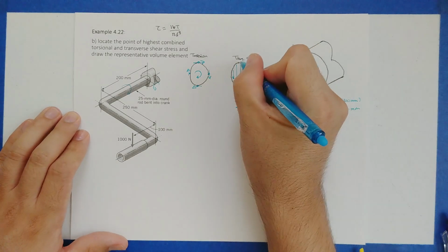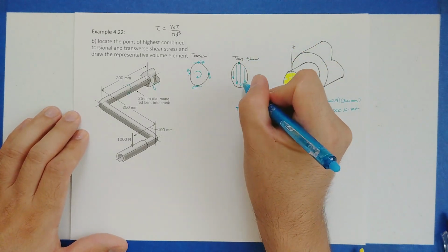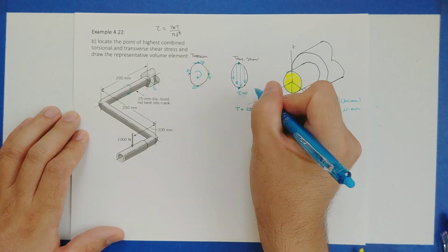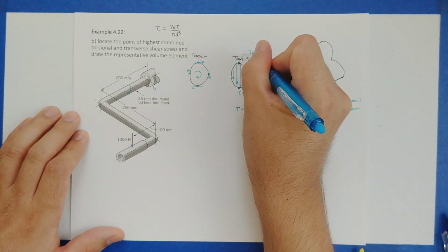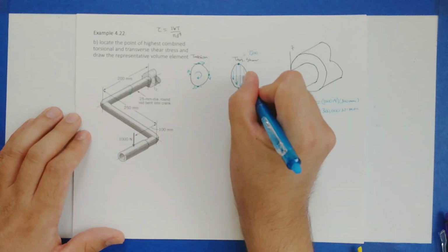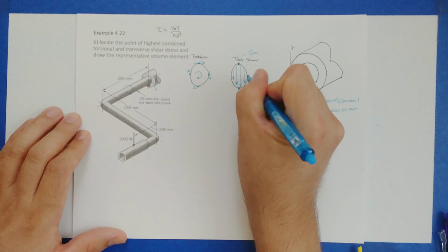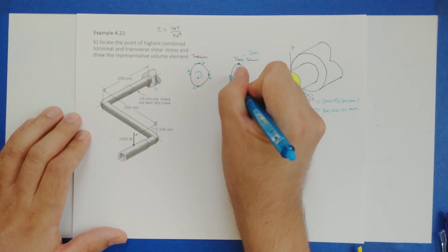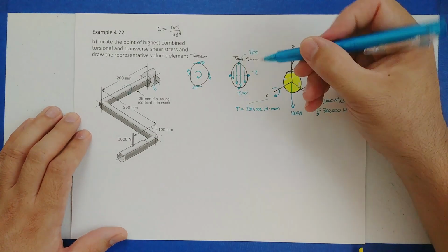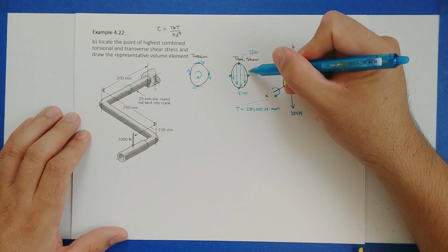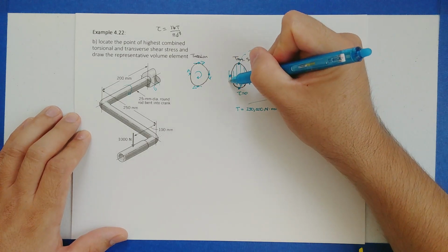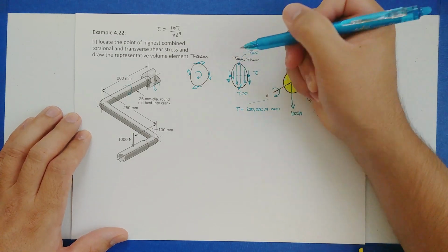You should already know from solids that if we look at the very top and the bottom point for a transverse shear, this is going to be 0. We cannot generate there, but it's going to be maximum over here, these axes over here. So this is going to be the max. What direction is it going to be? Well, it's going to be the same direction as the arrow. So here we have something down like so, and on this one, we have an arrow pointing down.